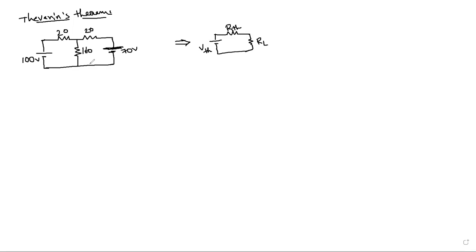That means in the problem they mentioned 160 ohm, correct? Out of three resistances, they mentioned one value. That will be your load resistor, remember. So here you need to calculate the amount of current passing through it as per the given problem. Therefore, from the given data, your RL value is 160 ohm. So you need to indicate it immediately in the equivalent circuit, and then calculate RTH and your